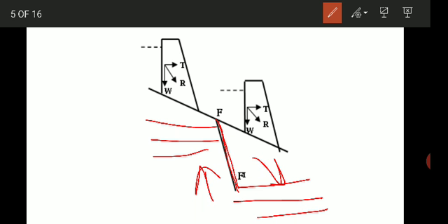I had told you, fault is what? The displacement of the beds along the crack, right? So along this fracture, the beds have displaced. So this is a cause for earthquake, right? And because of this reason, if you construct a dam in a faulted zone, there are more chances of earthquake again. So if a site has to be selected in such a zone, you have to see that the site has very few disadvantages and there should not be any serious defects.